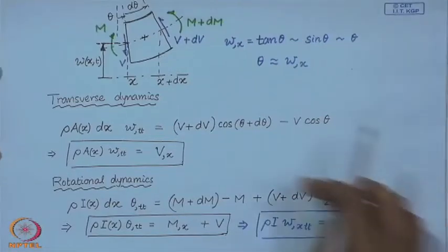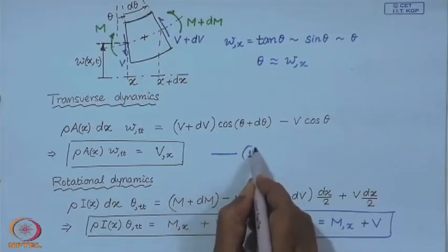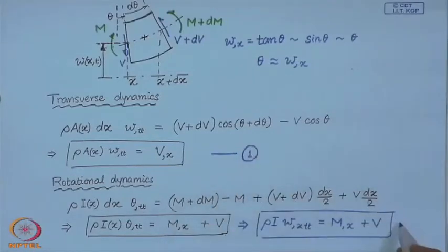now, you see in these two equations, the bending moment m we have represented in terms of the stress, which was calculated in terms of strain, which was calculated in terms of the deflection of the neutral axis, our field variable w.